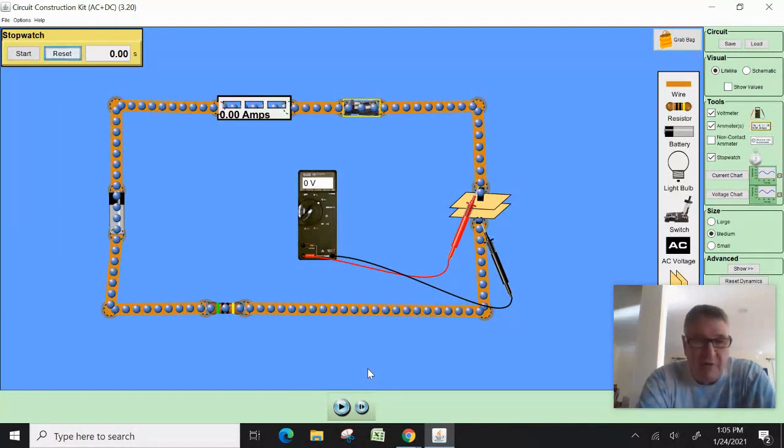Now the reason why the time is important, if you look at the top, it's beeping. If you look at the top of the lab, we didn't actually do this lab, but I showed you this lab. The RC is called the time constant. So if you take the resistance and you take the capacitance of the circuit, that gives you a time constant. If you multiply that time constant, the RC product, by 5, that's 5 time constant intervals. And what that means is that the capacitor is done doing what it's going to do. It's 99.3% of the way through what it's going to do. In other words, it's almost totally at equilibrium or steady state or whatever you want to call it.